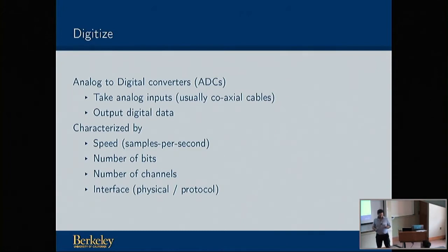How many samples per second do you get out of your ADC? As Deepti and some others have talked about, the faster you sample your analog streams, the more bandwidth you can capture and process in your digital system. The Nyquist criterion states that the amount of bandwidth you can process unambiguously without aliasing is half the sample rate. So faster samplers mean wider bandwidths you can process.